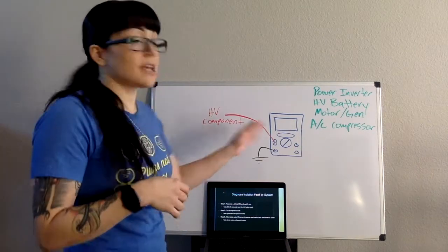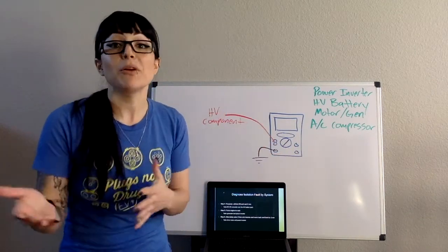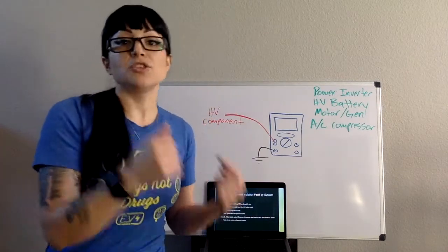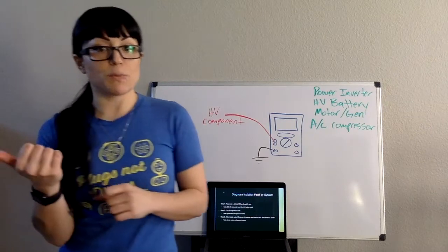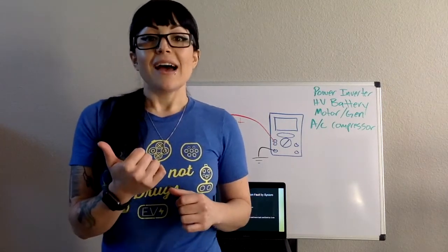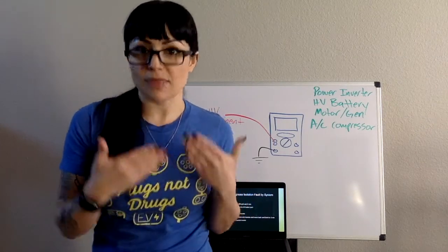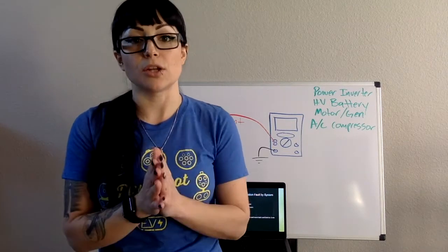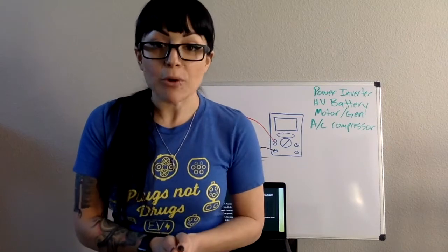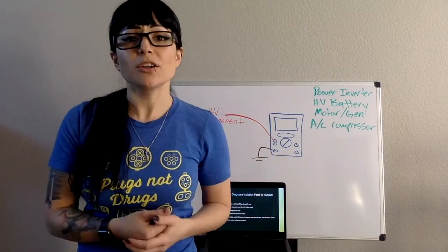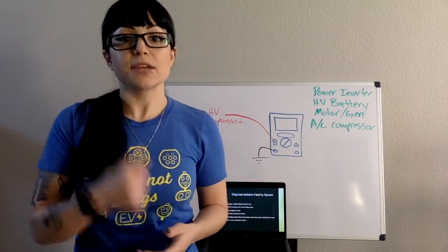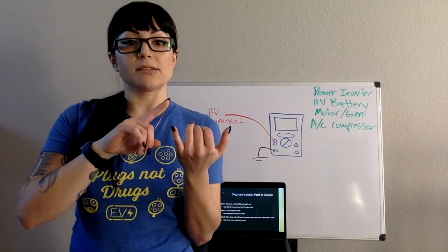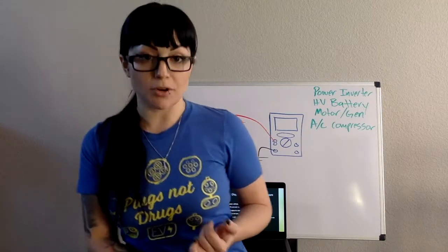And another thing that's connected to that is our power inverter. When I turn the engine on, it spins our generator, and the generator wants to send high voltage back to our high voltage battery pack. Something needs to control that, and that's our power inverter. So if there is an isolation fault in the power inverter, we are going to get a code once the engine kicks on as well. So when we force the engine on, we are testing the power inverter and the generator portion.